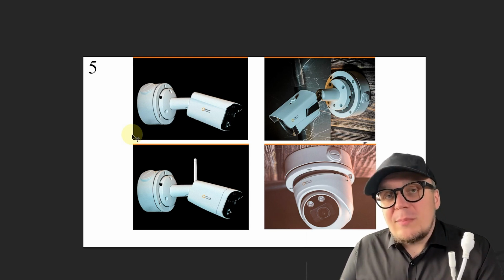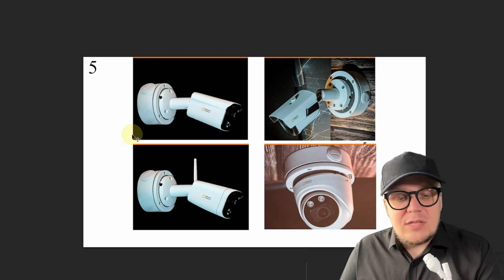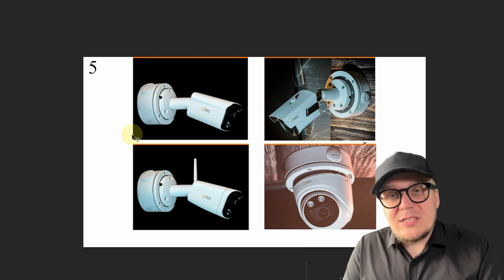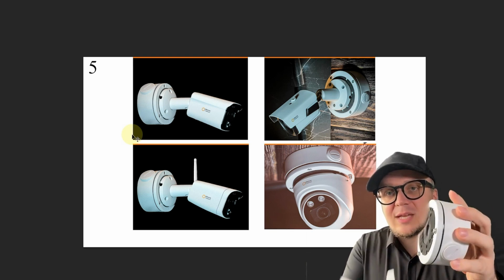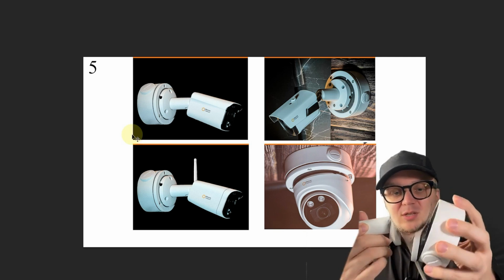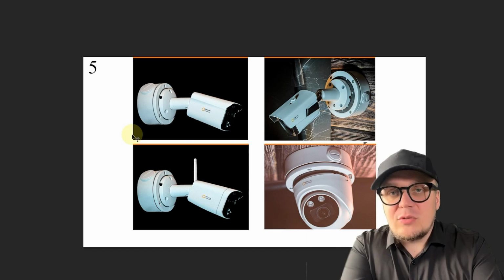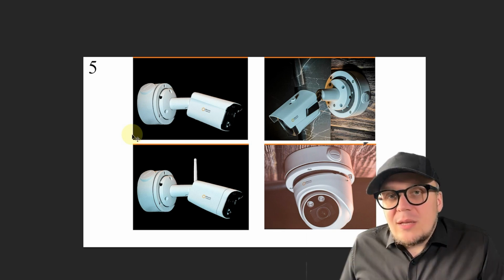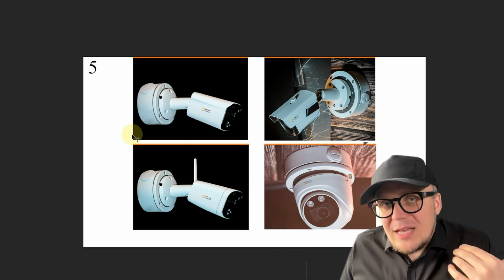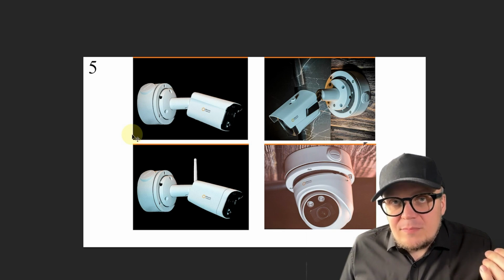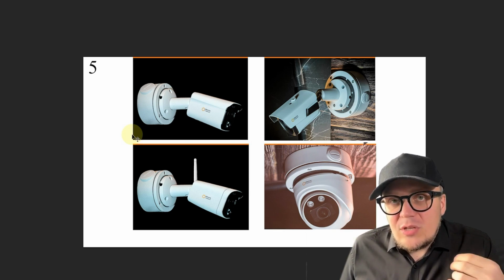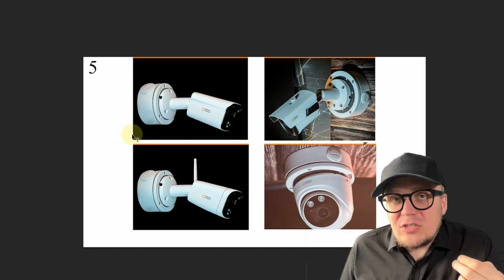Some people do this using makeshift methods like tape or electrical tape. The professional option involves installation of such bases. That is, the camera is mounted on this base and the connection is made inside this base. The camera is connected to the cable, which then goes to the video recorder. Many people think that if the surveillance camera is not placed in the open air, for example, if you install it under an awning somewhere outside, then such protection is not needed.